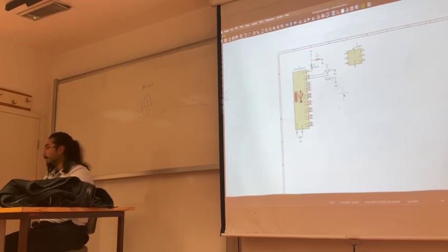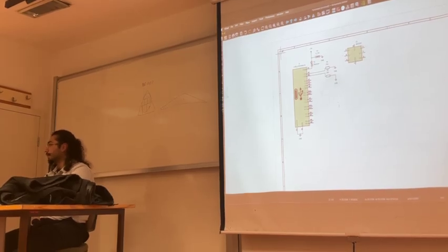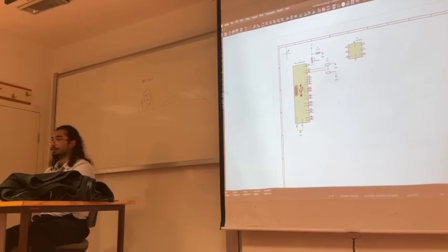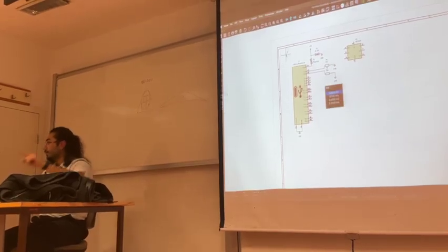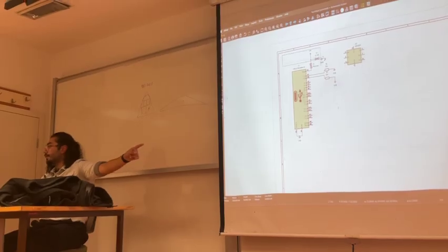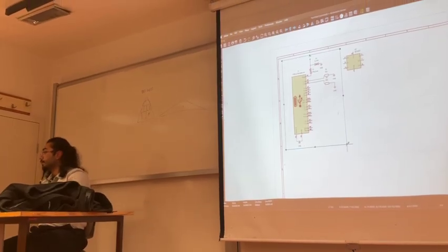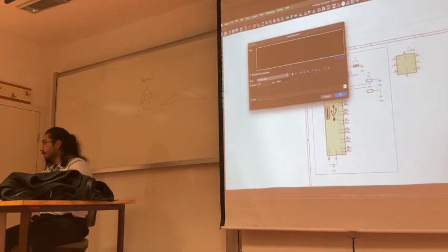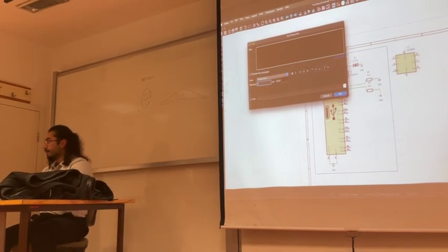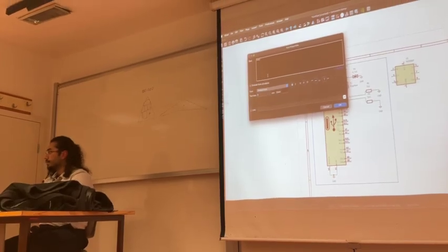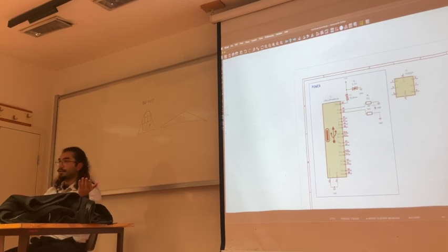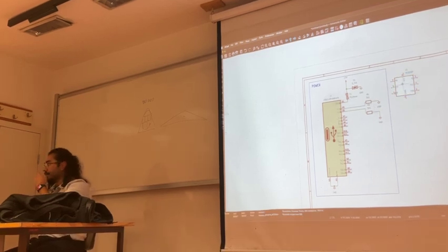So we are done with the power part. I just click on this square thingy. I come here. I make my grid larger by clicking on N and coming to 2.45. And adding my square like this. This is for labeling and compartmentalization, and this makes your schematic really easy to read. I come here, I make this larger, I make it bold, and I say power. And bam. You just labeled a schematic like an engineer. Congrats.